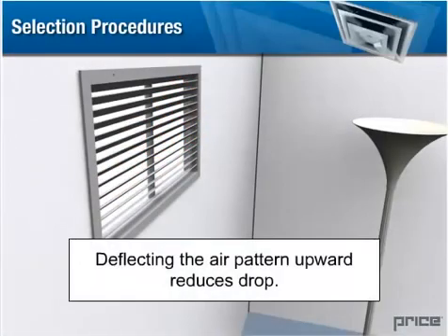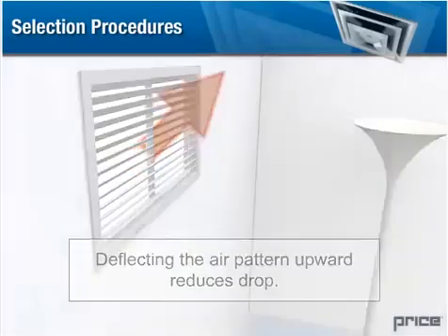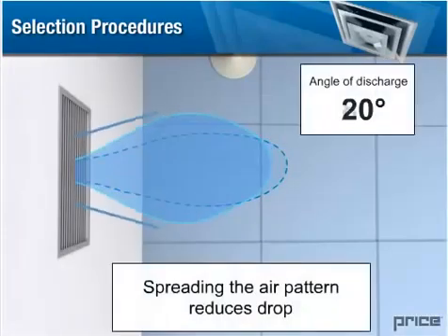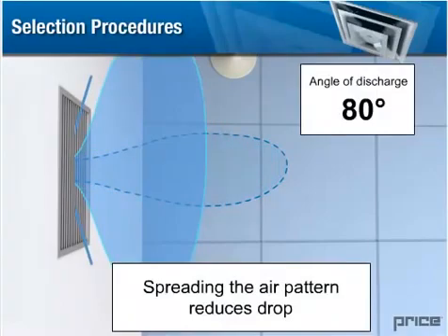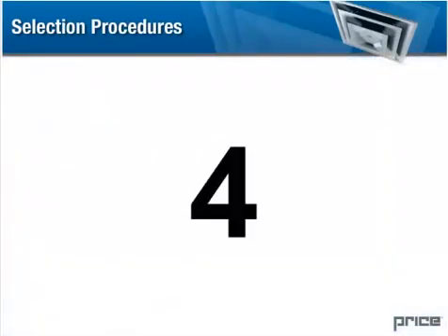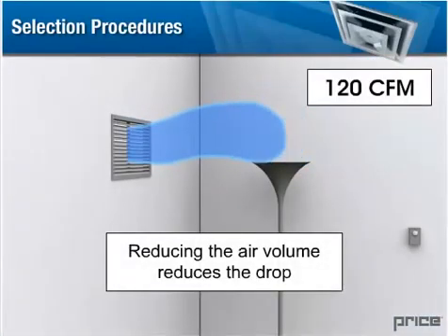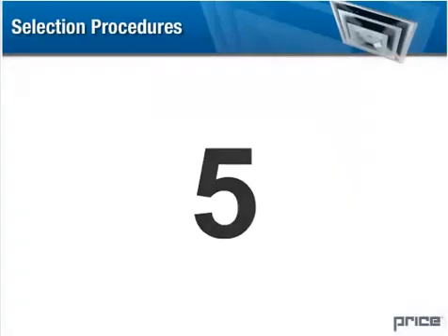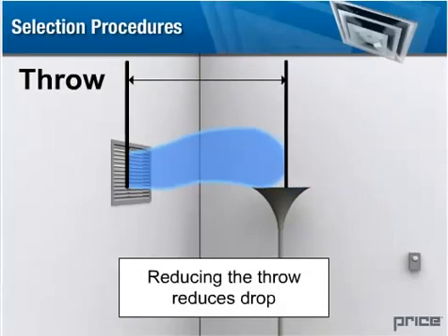2. Deflecting the air pattern upward reduces the drop. 3. Spreading the air pattern reduces the drop. 4. Reducing the air volume reduces drop. 5. Reducing the throw reduces drop.